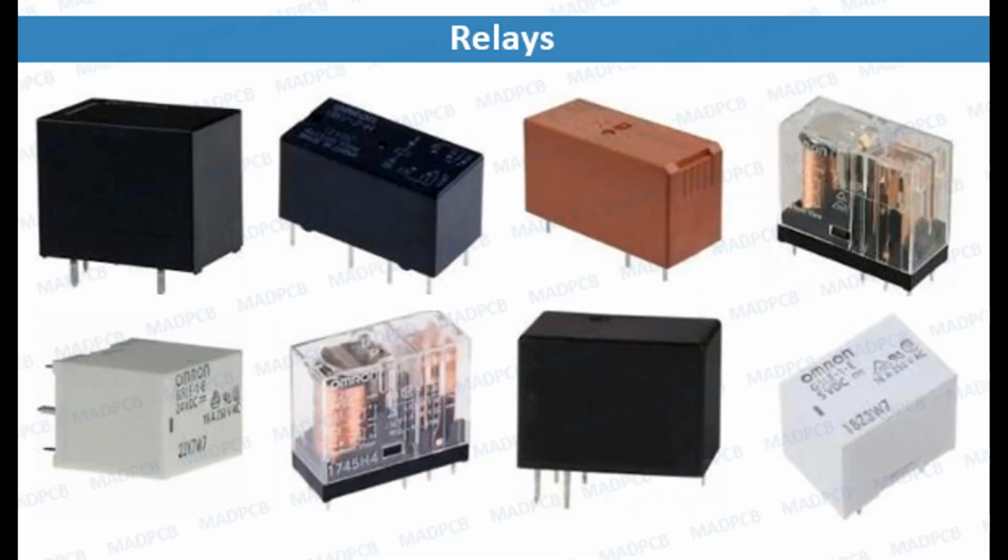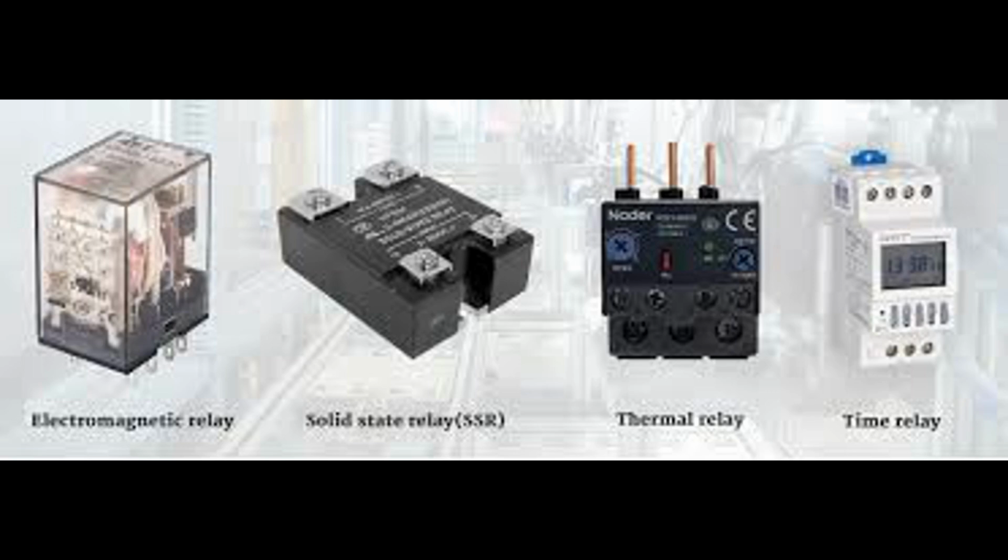control applications. A differential relay is a protective relay designed to detect faults within a specified area of an electrical system, typically by comparing the difference between incoming and outgoing currents. This relay is used primarily in power systems to protect critical equipment, such as transformers, generators, and bus bars, from internal faults. If the current difference exceeds a certain threshold, indicating a fault within the protected zone, the relay will trip and disconnect the affected equipment to prevent damage.